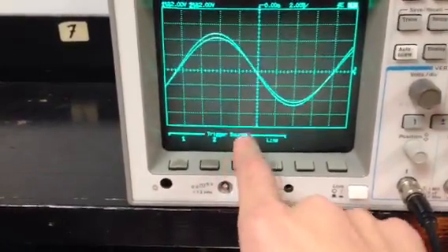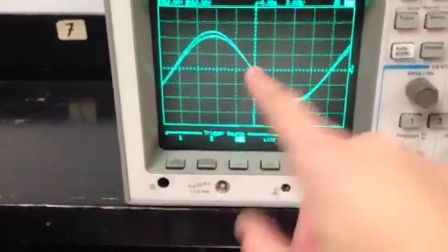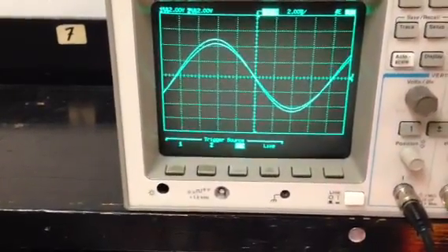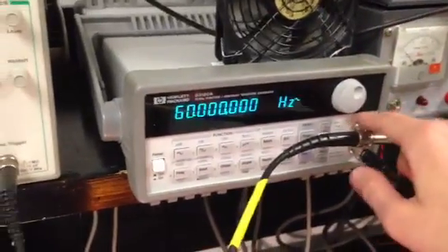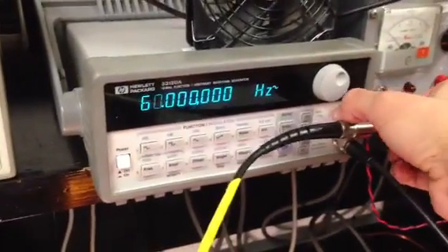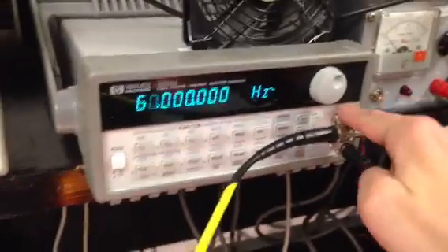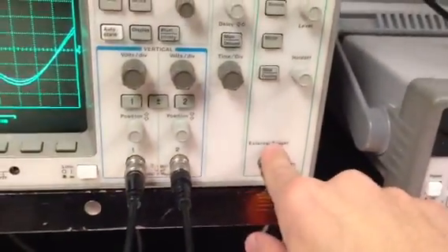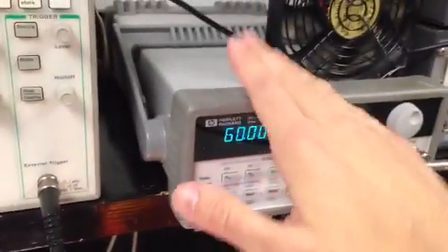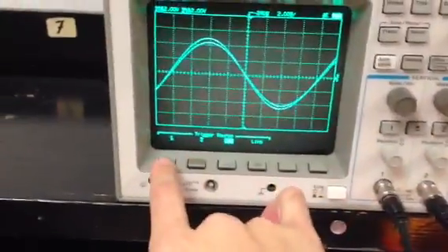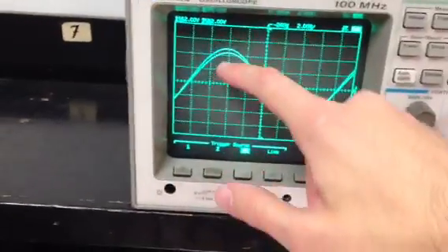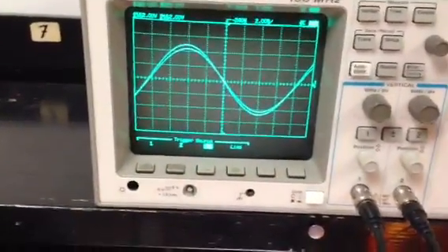One thing that'll make your life a lot easier is if you trigger externally. Your function generator generates a pulse, so basically you want to take a BNC to BNC cable and connect it from sync to external trigger. What this guy does is it creates a clock that is fed to this guy and tells this guy when to sync up, versus if I change to trigger source 1 or 2, it's looking for a particular voltage and is trying to trigger off that voltage.